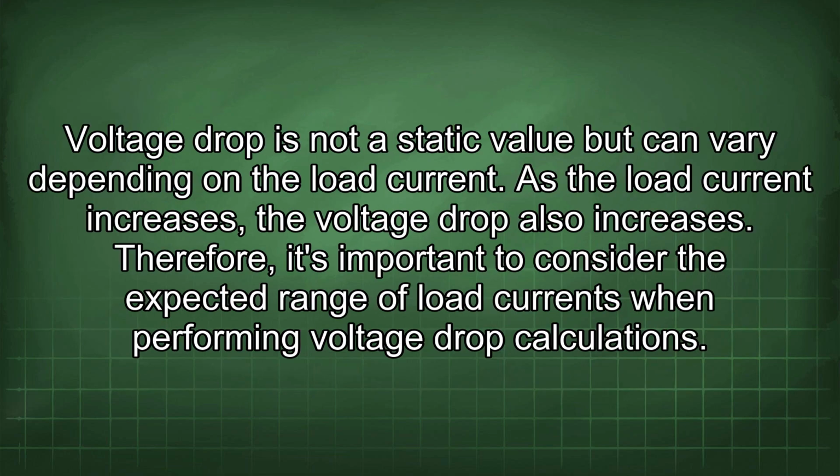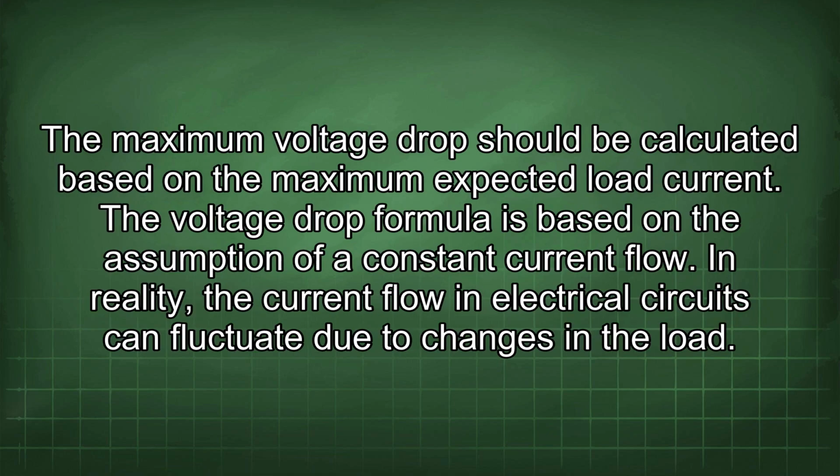Voltage drop is not a static value but can vary depending on the load current. As the load current increases, the voltage drop also increases. Therefore, it's important to consider the expected range of load current when performing voltage drop calculations. The maximum voltage drop should be calculated based on the maximum expected load current.